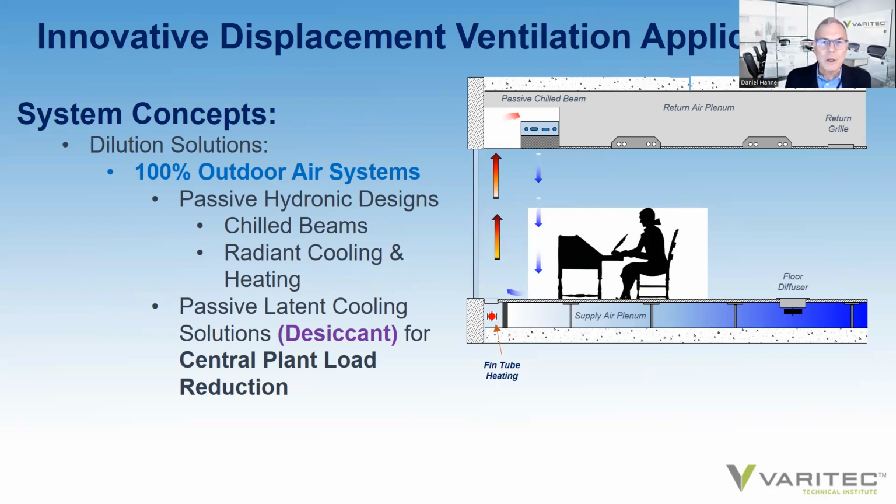What if you used an underfloor air system with displacement ventilation that is 100% outside air, no return air back to the building, no active agent pathogens being entrained in the return air and resupplied to the building because of MERV 13 filtration? What if we just control the air change rates to a space using 100% outside air, and outside air only crosses the breathing zone in a thermally stratified environment? Is that doable? And the answer is yes.